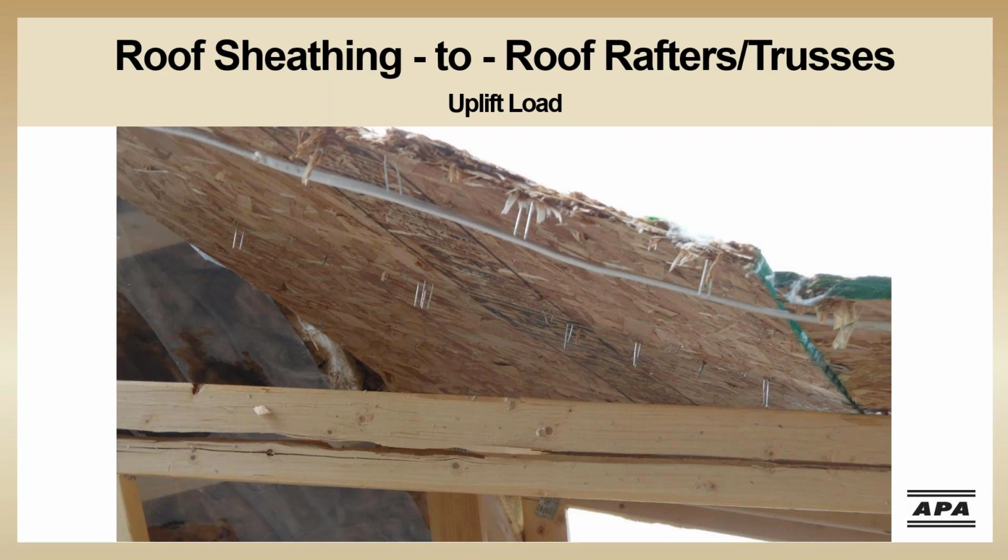In this photo, the roof sheathing staples pulled out of the roof framing member during a tornado. Staples are an acceptable fastener per the IRC, but are required to be installed at a tighter spacing than nails. IRC Table R602.3(2) provides the required spacing for alternate attachment methods, including staples. Staples should also be oriented properly during installation, with the staple aligned parallel to the roof framing member.